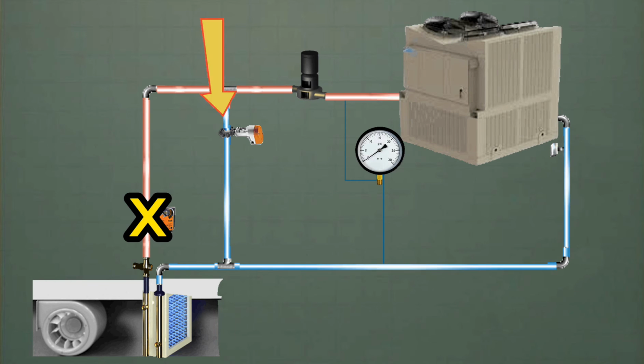It opened to 100%, boom, lost flow. We didn't trip on low suction pressure, but we lost flow. So with the machine still off, I went out to the chiller again, checked my pressure drop again, and I saw, oh, okay, now I have no flow or very little flow. Like not measurable. I couldn't measure my pressure drop anymore with a gauge.